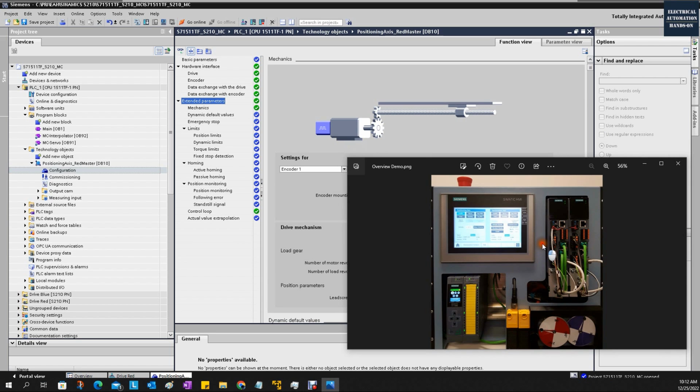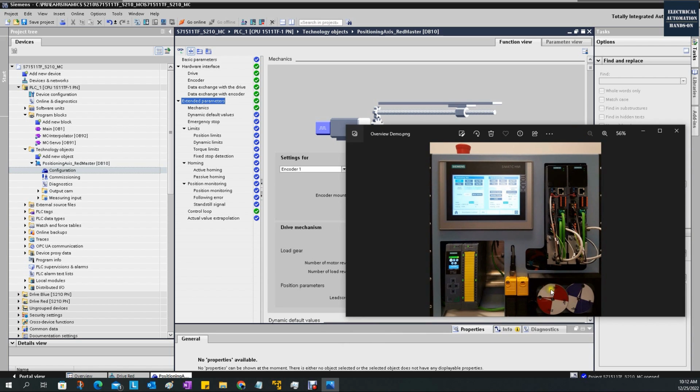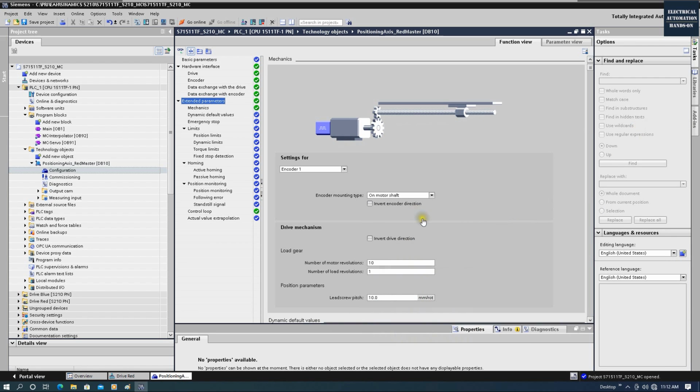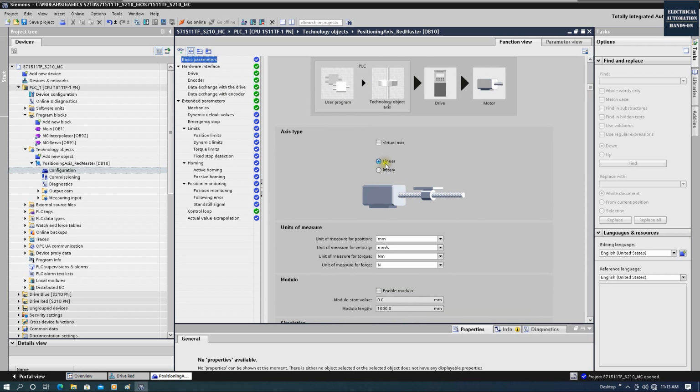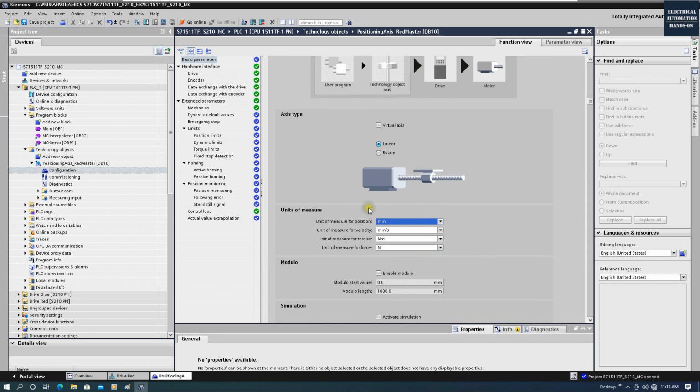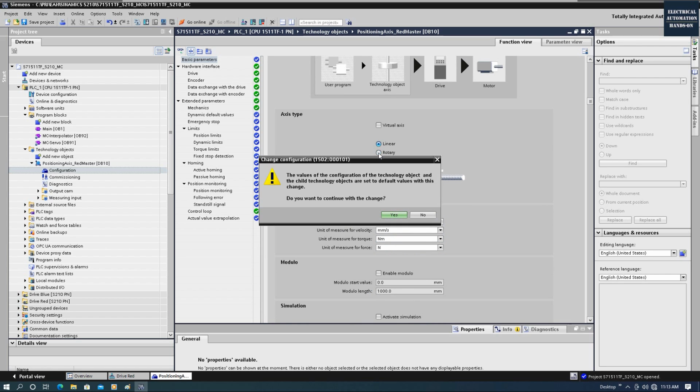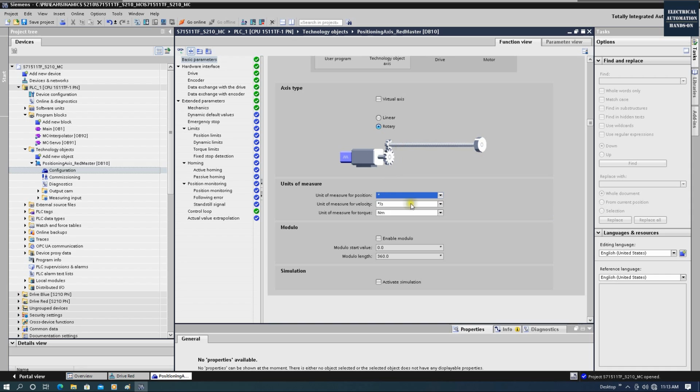So in this case, as you remember from this demo, I'm using this rotary disc to test. So basically, if I set the degree, it will be quite straightforward. So we will see, for example, when I control 360, then it can spin 1 revolution, right? So I can set this entire scenario as the rotary application. Then let's go back to the basic. So the basic here, default, that's the linear. And we can configure the millimeter and the units. We can shift to the rotary. So it can automatically change to degrees and rates. Okay, and torque, that is newton meter.